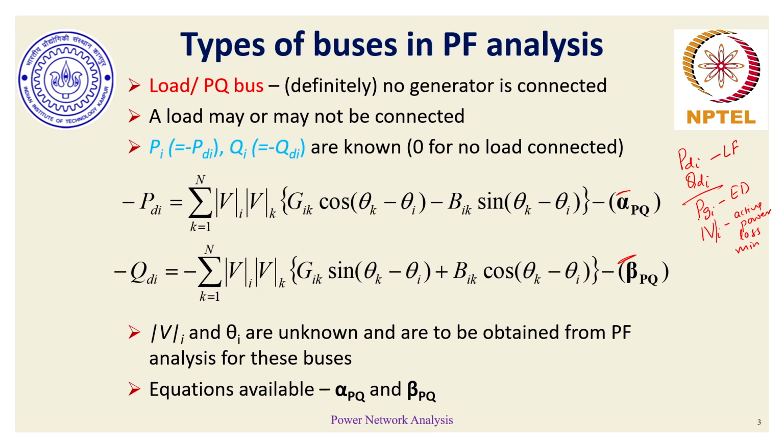So these quantities can be known for the generators and these could be known from loads. So can this information not be used to understand the classification of buses and bring in consistency between number of equations and number of unknowns?